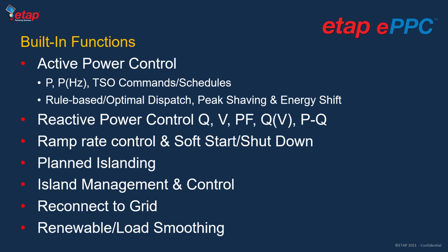Reactive power control functions allow QV, power factor, and voltage control at the point of interconnection. Ramp rate control is applicable to both active and reactive power controls. Soft start can be applied to a plant collector.